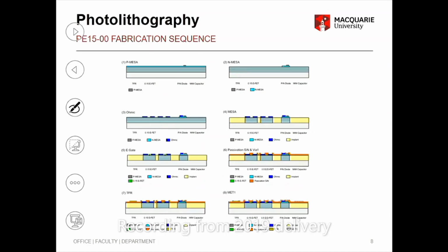So when you're building it up, are you just blasting with light right at the end, or is it one layer blast and another layer blast? Yeah. So you do one layer, mask, blast, maybe clean up, then another layer. So it's a longer process. When you do a wafer, that's why when you make your circuits, you put all your circuits in one reticle, and then you'll have a mask for each layer, right?